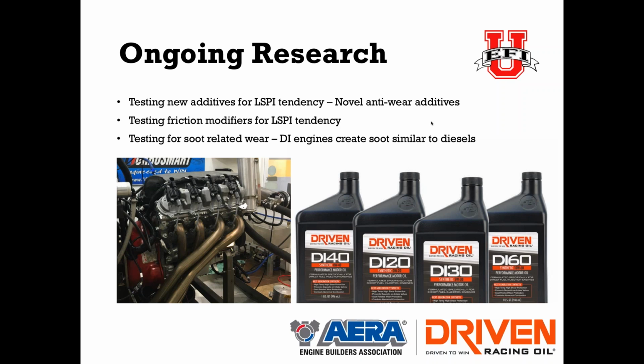So are there other additives we can add to the oil that complement the ZDDP that might have that same kind of reducing effect of LSPI? So we want to look at that. Also, we want to see for friction modifiers, to improve fuel efficiency. Are there friction modifiers like moly that also provide that? Moly carries sulfur, and that's the downside, is that when you add sulfur, then there's a sulfur limit on these oils, and they want the sulfur level lower. So are there non-sulfur carrying friction modifiers?